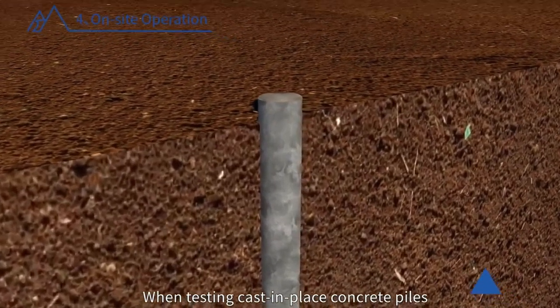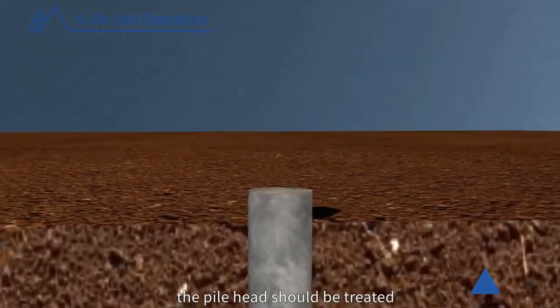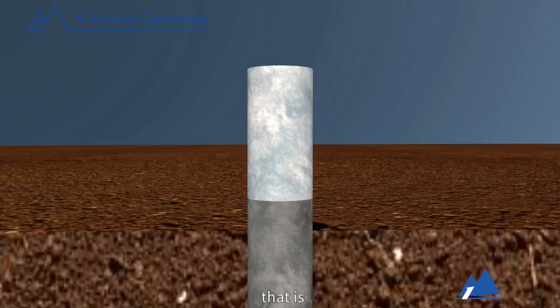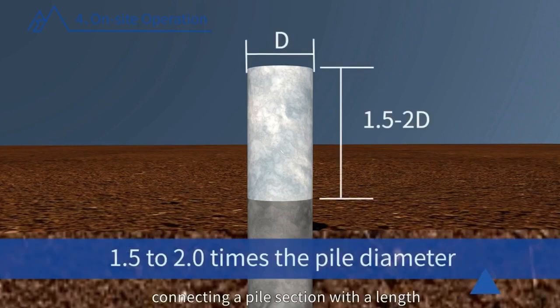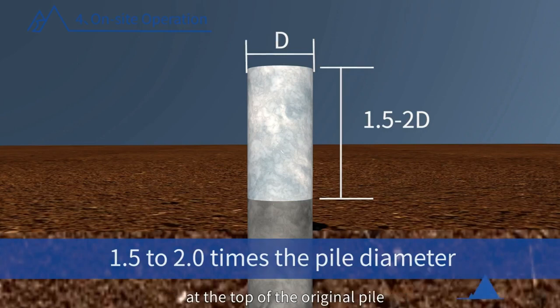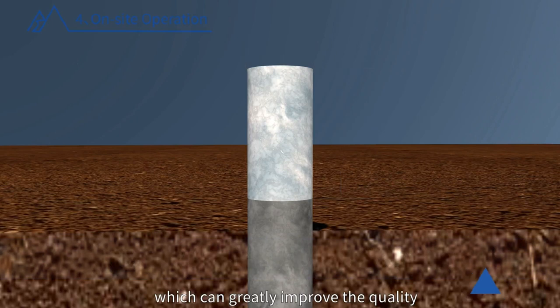When testing cast-in-place concrete piles, the pile head should be treated by increasing the length of the pile as much as possible. That is, connecting a pile section with a length of 1.5 to 2.0 times the pile diameter at the top of the original pile, which can greatly improve the quality of the collected data.